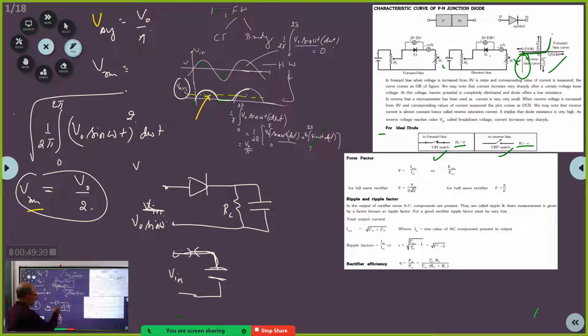On the other hand, when the waveform here is like this, then what will be there in this capacitor? As far as charging the capacitor is concerned, the current should flow only in one direction. Here the current is flowing both ways, therefore no charge will be sustained, because the average of the waveform you are feeding is 0.